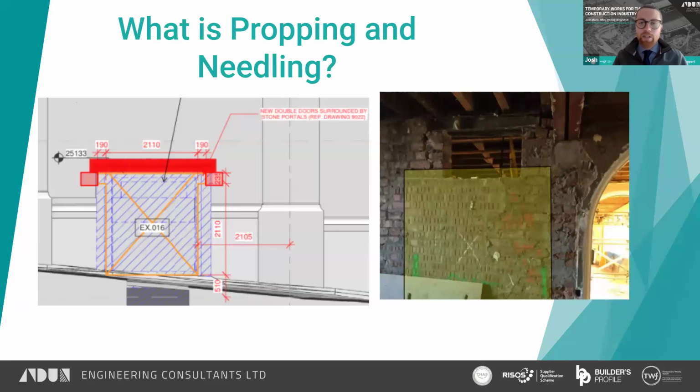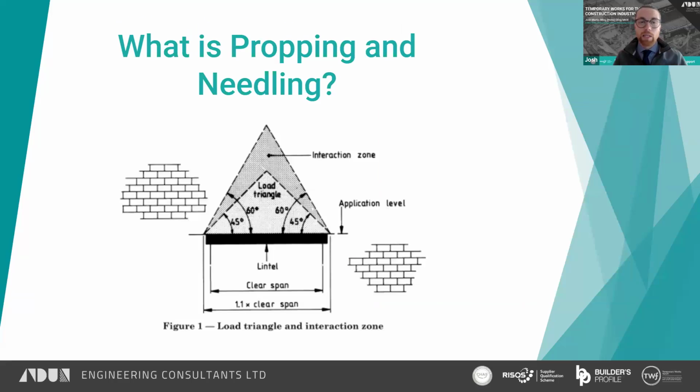And what we have is an existing load-bearing wall, be that of any construction, which is typically masonry or concrete block or concrete. And then the scope is to open up the wall, but we need to understand what this wall is doing in the first place, and the loadings that it currently is supporting, because this is really going to be important to provide the support in the temporary term. So why can't you just knock the wall down and whack a beam in?